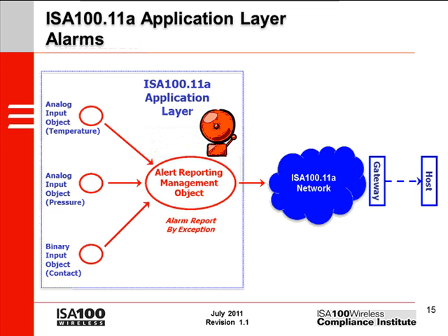Then we have alarms. Between publications, if trigger points are crossed, an exception is immediately reported through the gateway. In most applications, there shouldn't be a lot of exceptions, so alarms shouldn't use a lot of energy or network capacity. But the network does need to be properly designed so that exceptions propagate quickly and reliably.